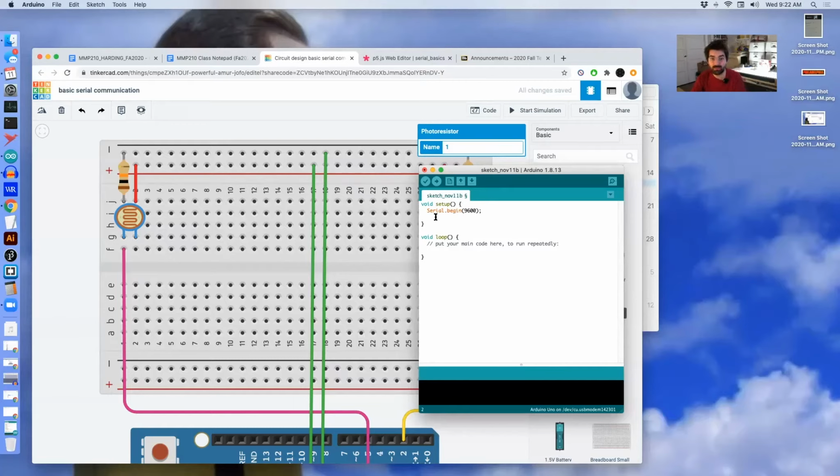So once we have the serial.begin put into our setup function, now we need to use it in our loop function. So I'll say serial.println. So print ln, that is an L, a lowercase l. And case matters, whether things are capital or lowercase are important here. So make sure that you are following along to the letter. And so in here, I'm just going to say hello in quotes. And once again, end that with my semicolon.